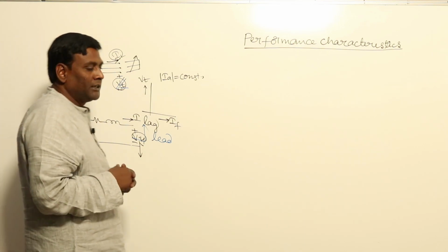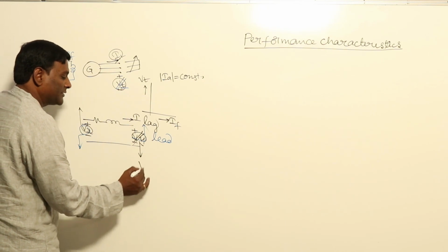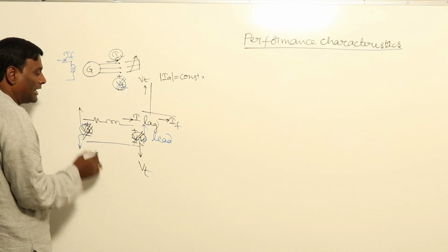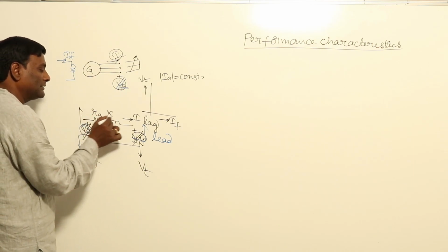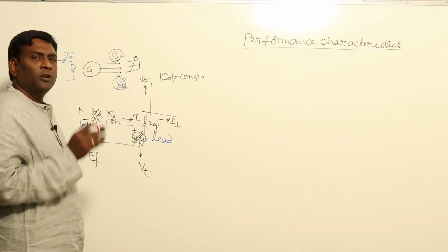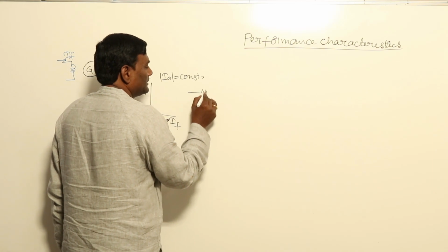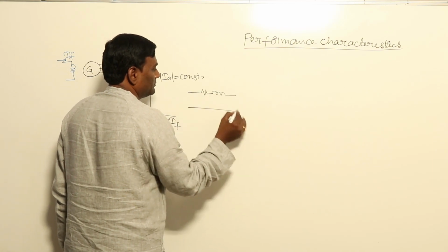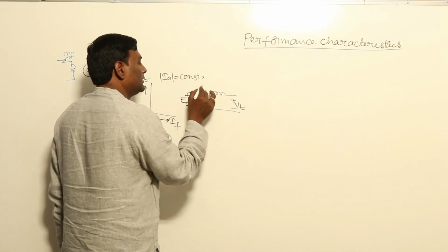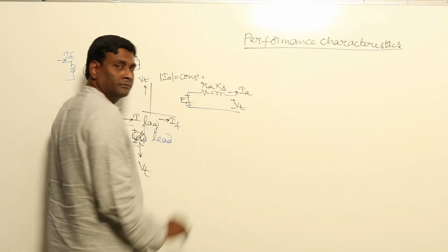That's it. Now, in our alternator, let me keep this Vy as Vt, the terminal voltage, this Vx as Ef, and let me keep this as Ra and Xs, or Ra can be neglected, only Xs. Now let us try to draw a small phasor diagram: resistance, reactance, Vt, Ef, Ra, Xs, Ia, alternator.